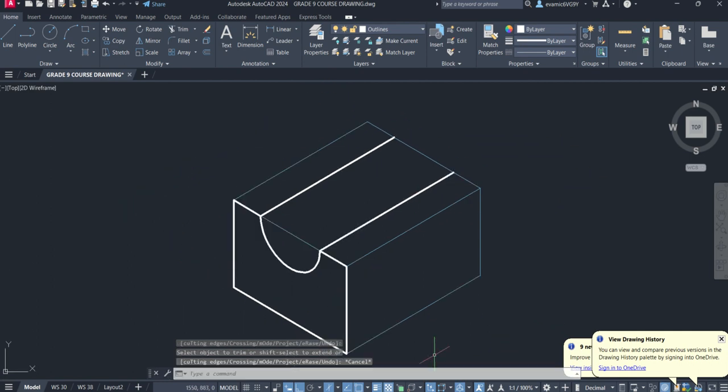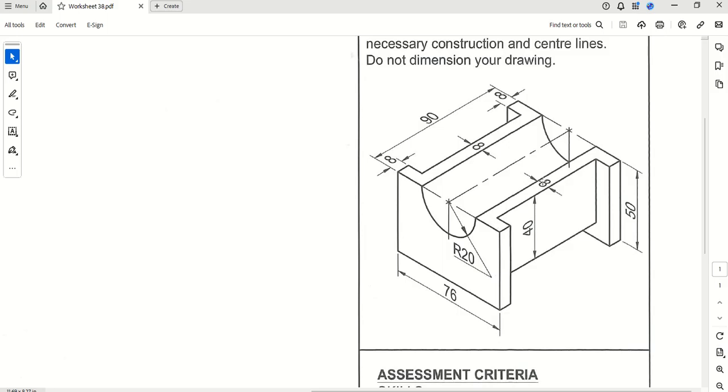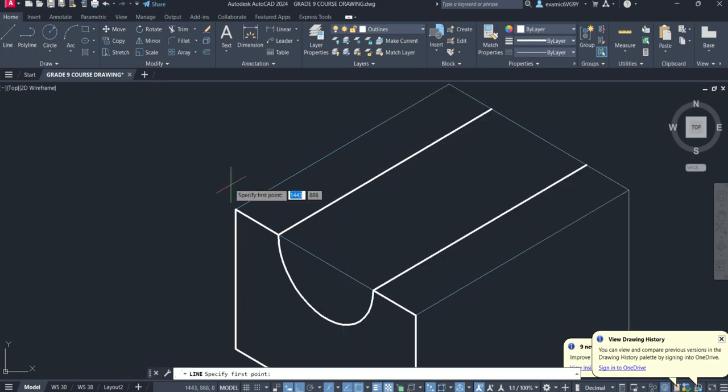From there, I'm going to work in those little C shapes that we have at the top there, that connect both base edges, and we know we've got a total of 8 mils in width along that whole space there, that whole face. So we're going to work off the edges here. I'm going to work off 8 from that corner there, 8 and enter. I'm going to come back here, space bar to re-engage the command that I've just used, 8 from there.